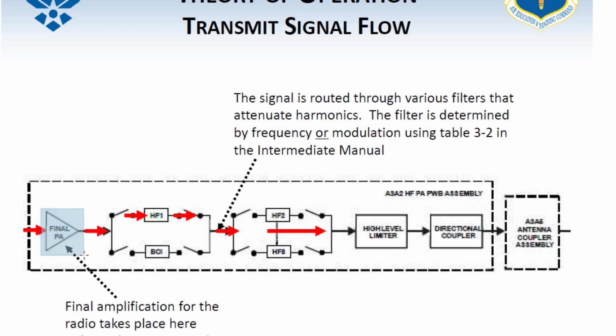One thing to note when we come to this next section, the final PA, you do not need to use that portion of the radio. It doesn't go through this again if you have that external power amp hooked up. Now, whether you have it hooked up or not, it's going to use this, and then we're going to go through what's known as the post-selector filter section of the radio. Why do you think it's called the post-selector filter section? Because it's after all the selection. It's after everything else that happened in the radio. It's happening at the very end. Very good. It's that epilogue.